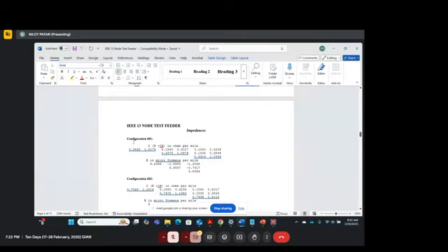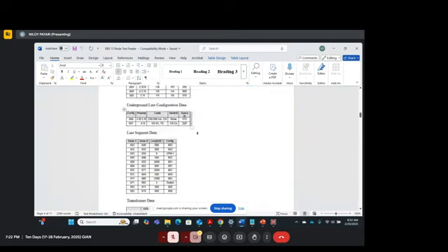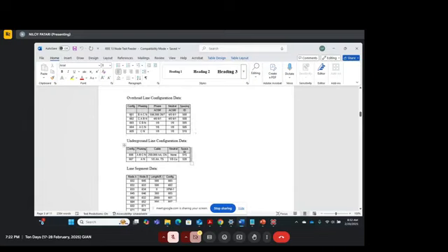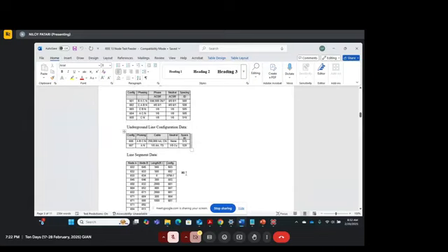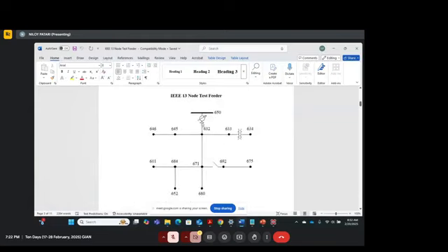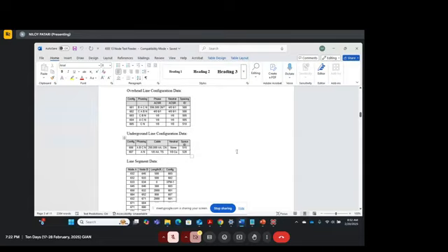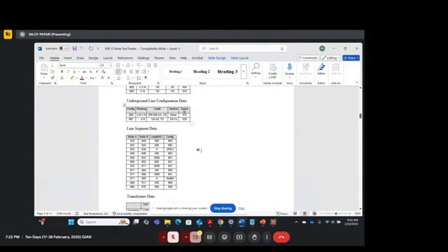So when you have a configuration 601, suppose, where is configuration 601? So 601 is this configuration, right? And 601 connects 650 and 632, and the length of the line is 2000 feet. So 650 and 632 is right up here, the substation end to the first node, right? So this particular line has a configuration of 601 and the length of the line is 2000 feet.